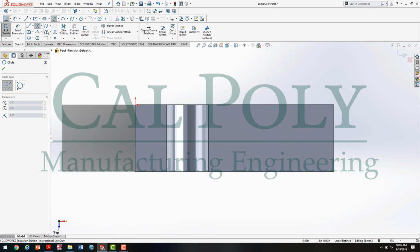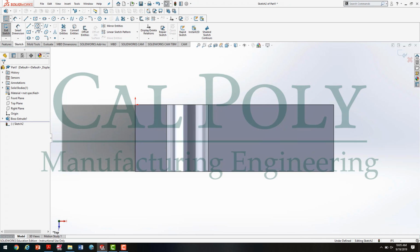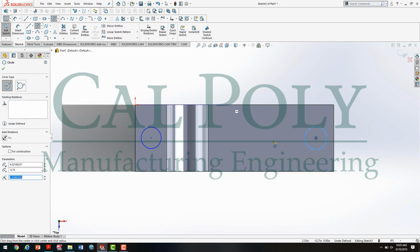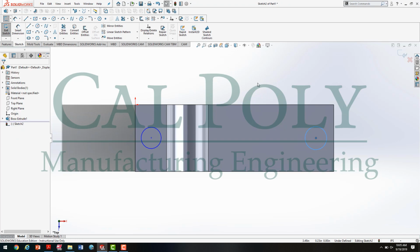So I'm going to click on my circle tool. Notice there's circle and perimeter circle, but I'm going to click on regular circle. I'm going to drag a circle out. If I really wanted to, I could get a midpoint relationship like that, then drag it out, but I'm still going to define it with a smart dimension so it can't move. Now at this point, I've got two circles. Notice they're not fully defined, their size and locations.